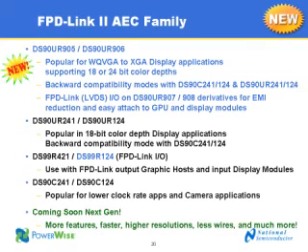DS90UR907-908. The main difference there is that instead of using the LVCMOS parallel interface, the other SerDes set will be using an FPD-Link interface. The FPD-Link interface allows you to connect to different displays and to different video sources, and really the FPD-Link interface allows you to take your EMI even to that next level. It provides a much more reduced EMI profile.